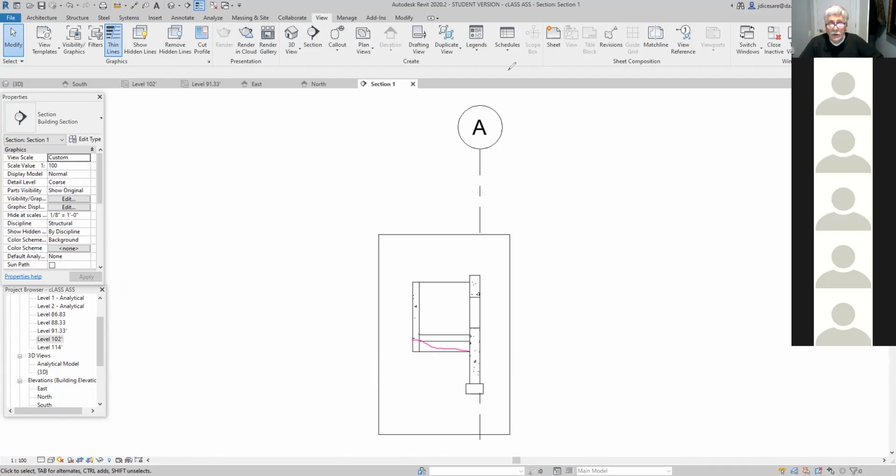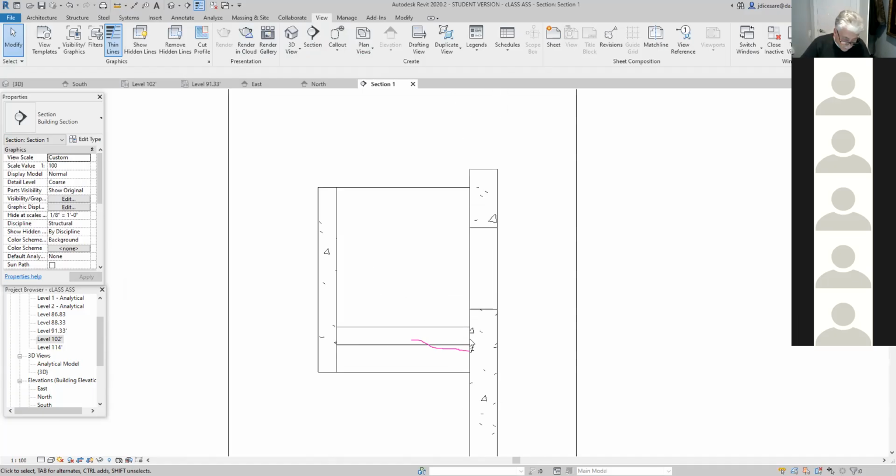So let me clear the drawing. Okay. Clear drawing. So there's a slab. It's where I want it to be. And to make absolutely sure, if I look at EE, the distance from the top of the opening to the top of the slab should be 8 inches. So if I do dimension from there to there, that's exactly where I want it to be. So perfect. It confirms that I placed it properly. Erase. Clear my drawing.